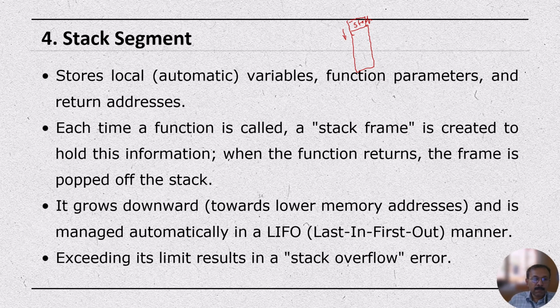Each time a function is called and returned, it uses the stack memory location to store the local variables and the program counter. Local variables use the stack memory because when the function goes out of scope, the stack memory gets cleared automatically.